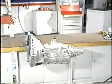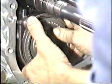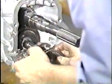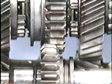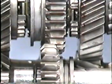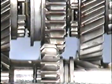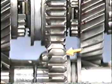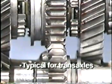Transmissions have used two very different approaches to reverse gear shifting. One approach uses a synchronizer and coupling sleeve, just as for all the forward gears. This is typical in the M50D, M5R2, and S542ZF. The other method of engaging reverse gear does not use a synchronizer. In this T50D transmission used in the Mustang, reverse is engaged by a movable idler gear, which slides into contact with spur gears on the countershaft and output shaft. A movable reverse idler gear is also typically used for reverse shifting in transaxles.